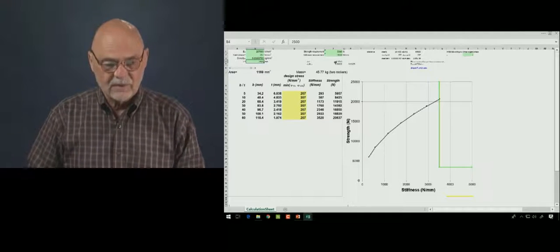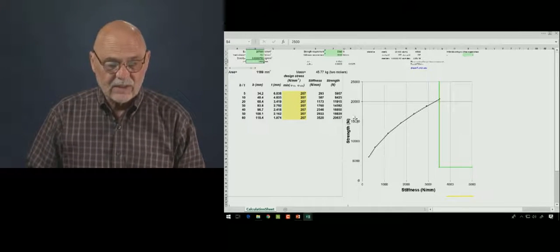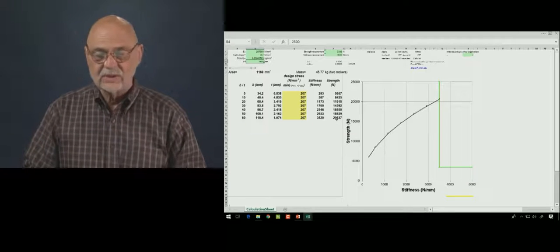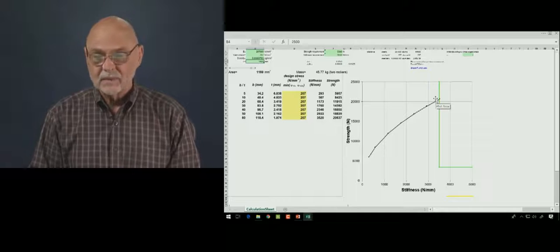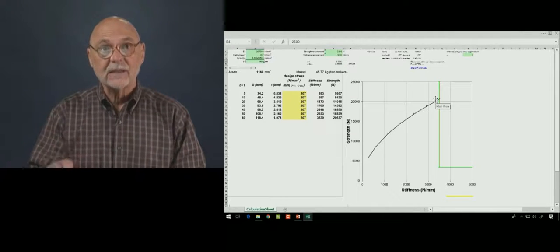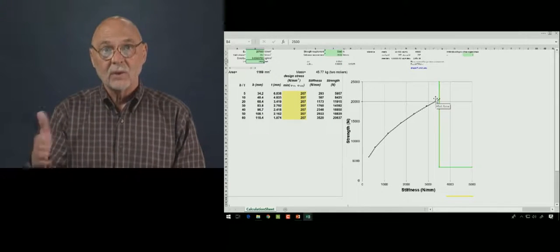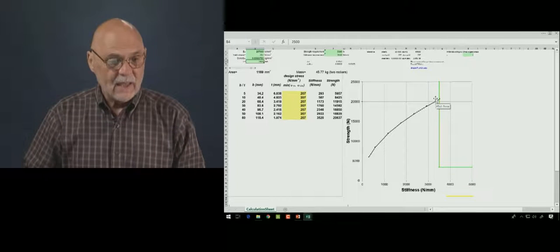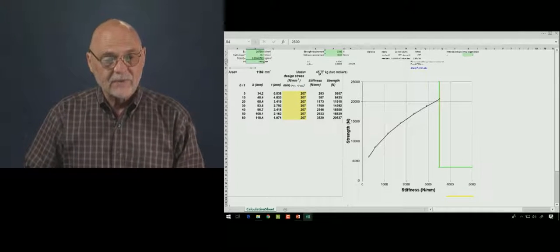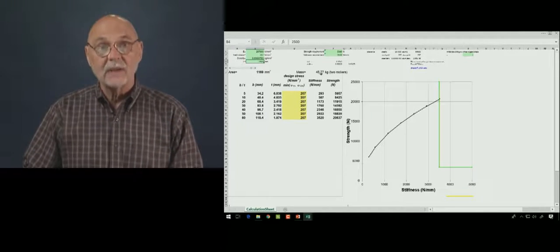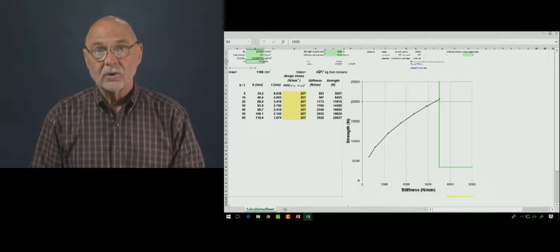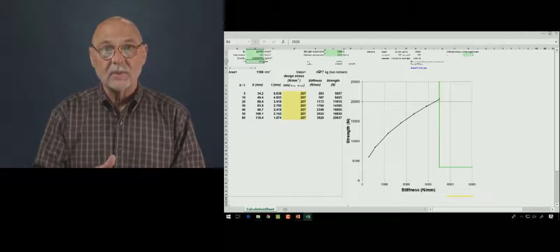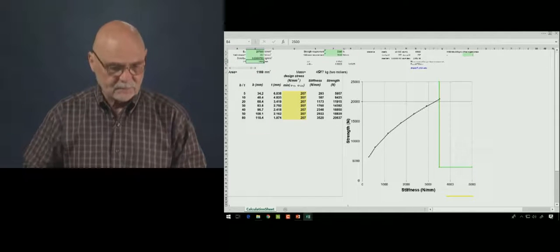So we have adequate stiffness. But look at the strength. It's at 20,600. So far exceeding the strength requirement, but it's the first thick wall design that actually meets both requirements simultaneously. And it has a mass of about 45.8 or so. So we really had to go a long way in order to additionally meet the stiffness requirement for this beam.